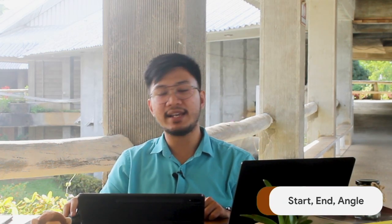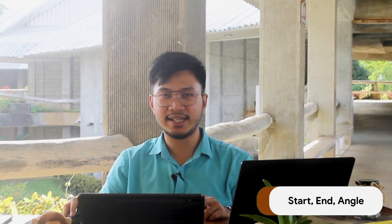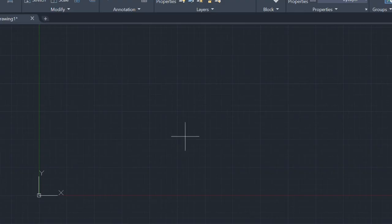Let's go to start, end, angle. So now, you're asked for the starting point, the ending point, and the angle. So again, your angle is the included angle of the start and end points of that arc.